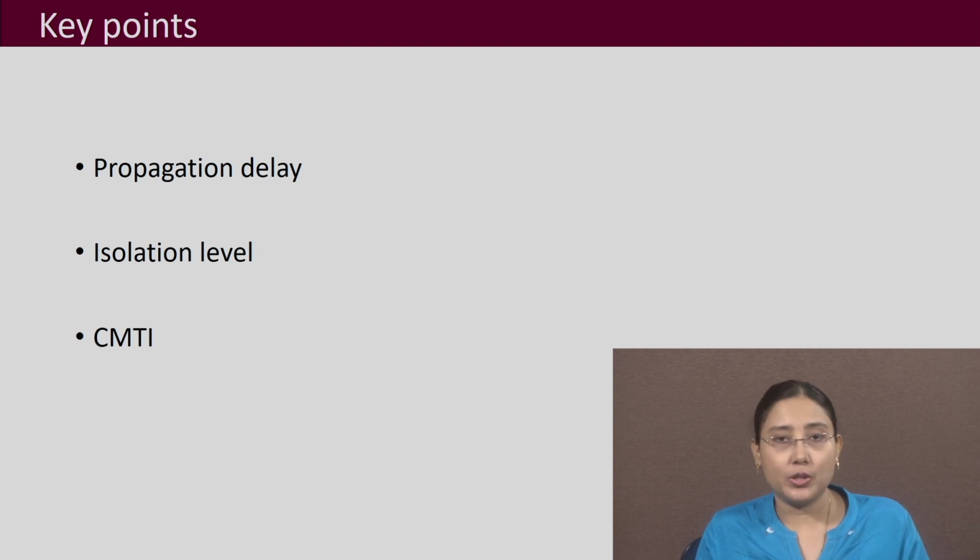You should check that it is not too high. Also associated with the capacitive coupling is your CMTI, common mode transient immunity. This level should be as high as possible, and it denotes how sensitive your driver is going to be to noise or the different transients and transitions that are going to happen in your power electronic circuit.